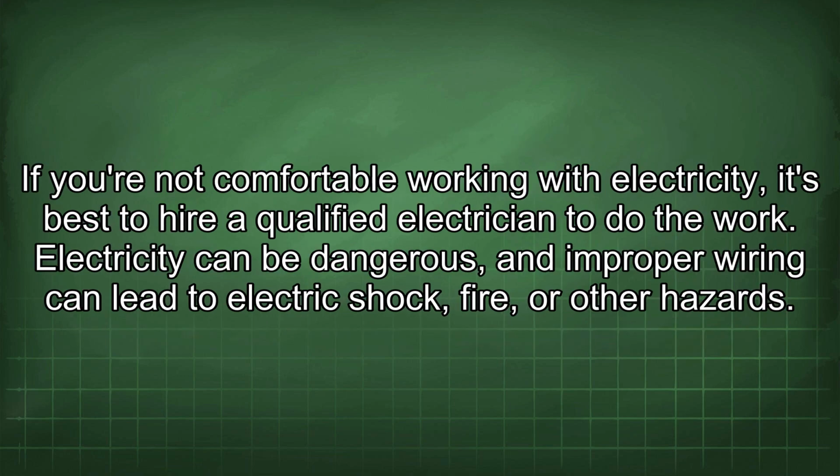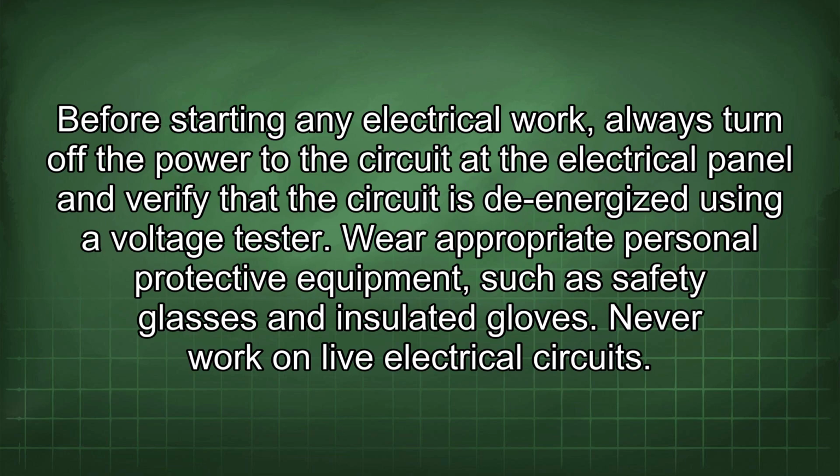If you're not comfortable working with electricity, it's best to hire a qualified electrician to do the work. Electricity can be dangerous, and improper wiring can lead to electric shock, fire, or other hazards. Before starting any electrical work, always turn off the power to the circuit at the electrical panel and verify that the circuit is de-energized using a voltage tester. Wear appropriate personal protective equipment, such as safety glasses and insulated gloves. Never work on live electrical circuits.